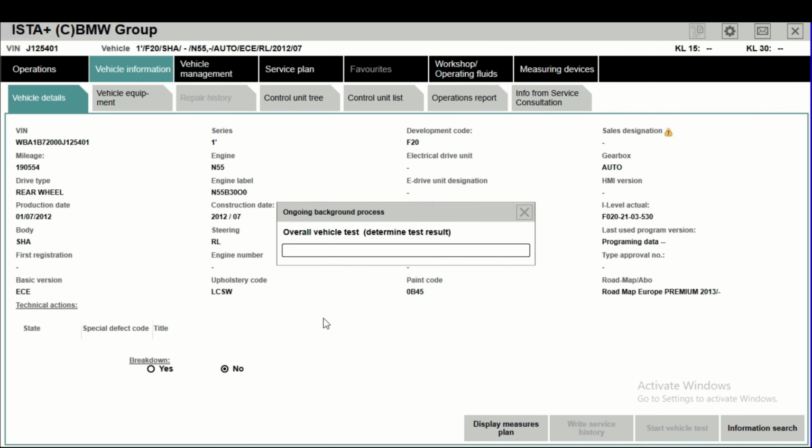It's not as easy as it was on the E-Series, so don't think you just need a MOST fiber port. There is no MOST fiber port like there is on the E60 anymore. There's a special way you have to do it. There is no MOST fiber port you plug in from the ICOM at all. It does not work like that anymore, so don't think you know how to do it, because you will not. It's very, very difficult, very technical, and you need to know what you're doing to pass it through the car, because it has to go through another system, through the ICOM to the car. Very difficult system to set up, but if you know how to do it, it's not. I will show that in another video, because I know you guys are going to be eager to program your car in the F-Series if you get one. That's something I'll show you later on.